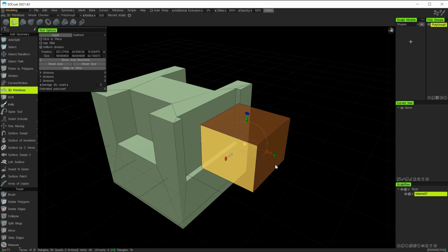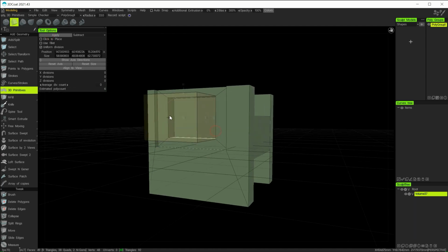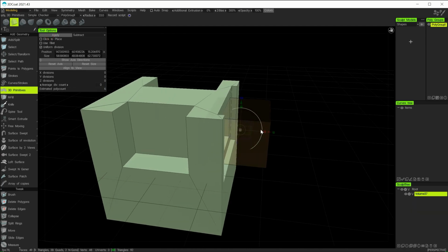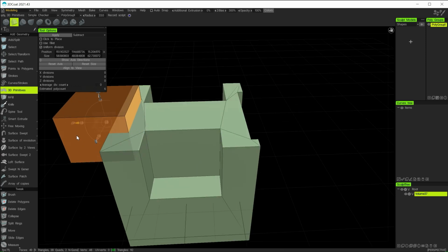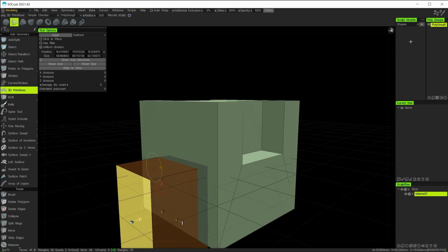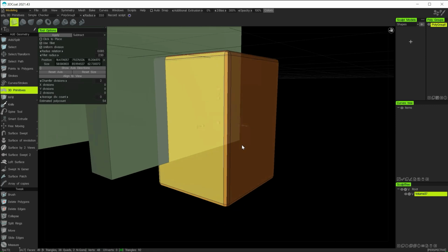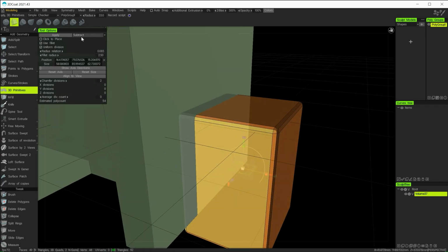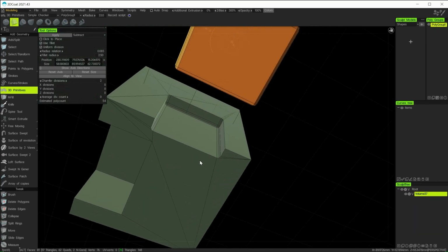I'll reduce that down, do one more, just a bevel cut into there, like so. So the other option I can do on here is using this cube. I can continue, and let's move it over onto this side, and you choose this face here. I'll just move it down here, scale it up, and I'll choose the fillet option. And you can see now I've got a filleted edge. So now I'll just cut into this green cube, like so, and you can see I did a pretty good job of cutting that out.